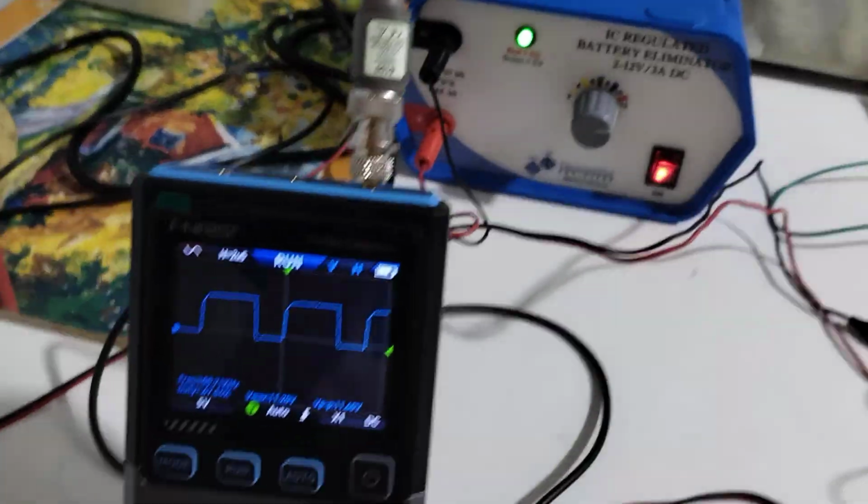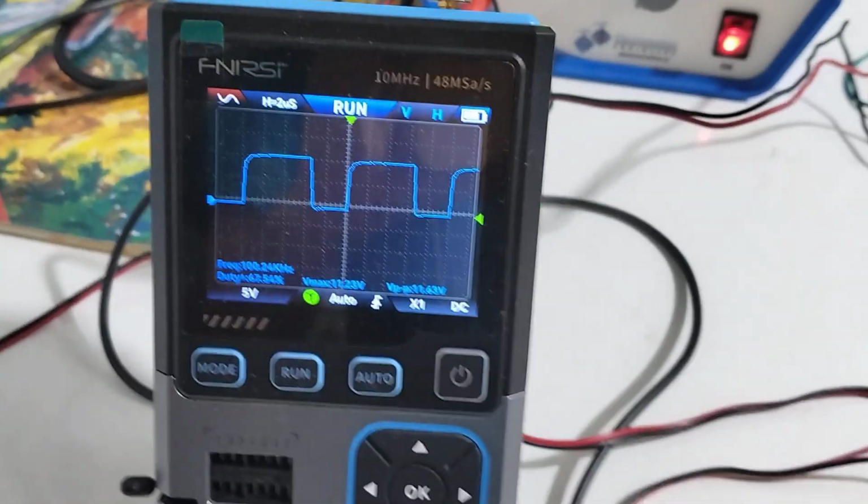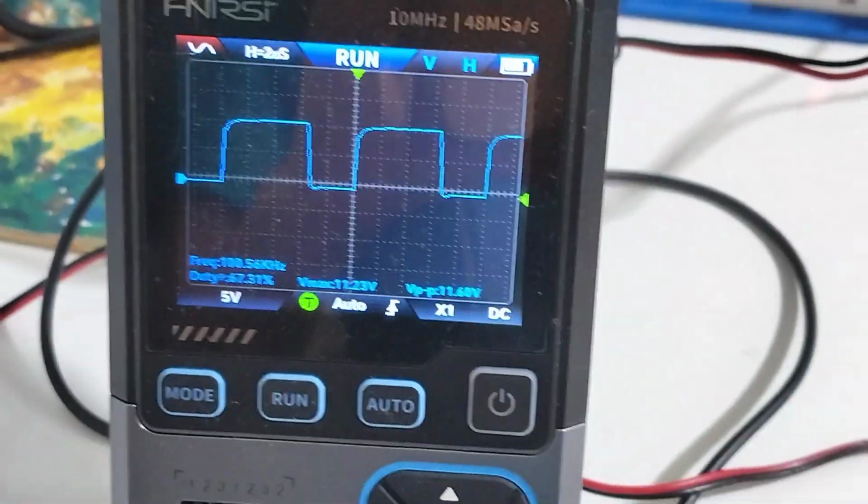And just to show you, right now you saw that it went to almost peak, 75% duty cycle, but we have clamped it, we're not allowing it to go above that, right? So if I just increase this a bit, let's maybe go to 80%, we can clamp it, not more than that. I'll flash this new code again, and you will see that we'll go even closer to our set point. Again, at 50 ohm load we can get closer to 30 volts, because we are letting it get more duty cycle. So now that I've flashed this again, I'll switch the power stage on.